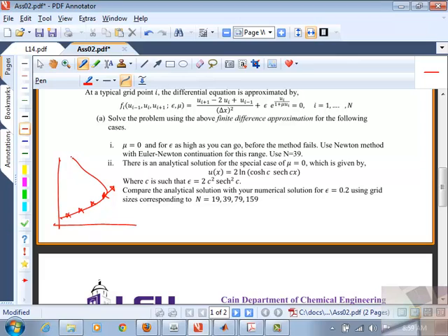And there's a message that says it's near singular point. That means that it's approaching this turning point? Yeah. The Jacobian becomes nearly singular. Okay. The condition for a limit point is the Jacobian must be exactly singular. Right? There must be exactly one eigenvalue that is 0. So the determinant must be 0. So you cannot invert that Jacobian.